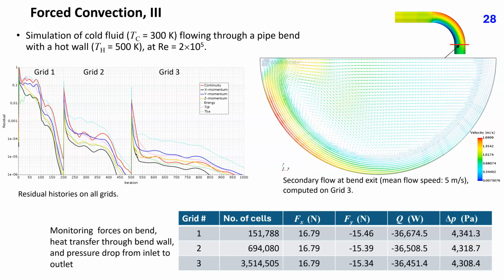This leads to a pressure-driven secondary flow, as shown in the vector plot in the cross-section at the exit from the bend. Shown are projections of velocity vectors onto the section plane. Along the wall, vectors are directed from the zone with high pressure toward the zone with low pressure. The low momentum fluid near the wall must flow in the direction of reducing pressure. In the symmetry plane, the fluid has more momentum and thus can flow against the pressure gradient, but it is slowing